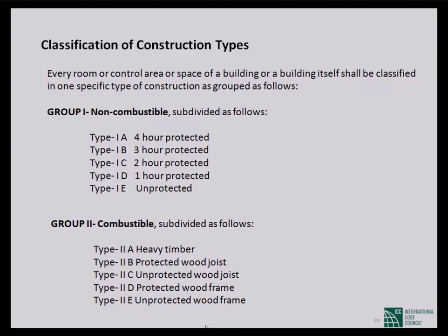That was something the same as the Indian standard. Indian standards classify buildings depending on their structure into type 1, type 2, type 3, type 4. They say type 1 is 4 hour, type 2 is 3 hour, type 3 is 2 hour, type 4 is 1 hour. Nothing was said about combustibility or non-combustibility in BNBC 2006, which is similar to the Indian standard.